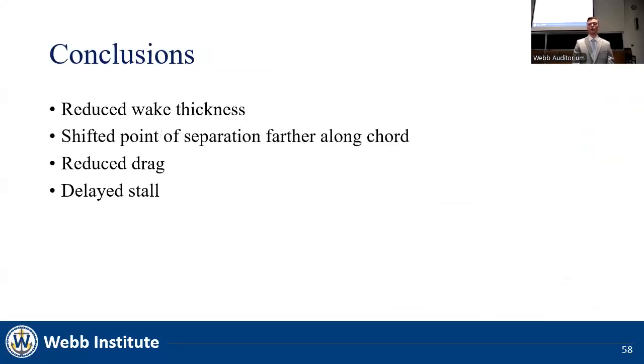In conclusion, the wavy leading edge consistently reduced wake thickness and pushed the point of separation further along the chord. This indicates a reduction in drag and delayed stall. In line with our objective, these factors demonstrate that a wavy leading edge rudder improves hydrodynamic performance when compared to a conventional leading edge at high angles of attack. This improvement seems to be the greatest at angles of attack closer to the stall angle and seems to be independent of Reynolds number over this range.